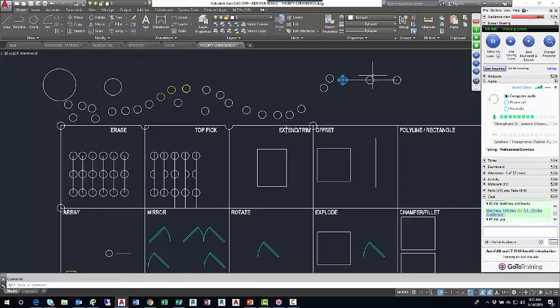So if I left click my 3 circles again, left click my horizontal line, and instead of hitting move, this time I hit copy. Go ahead and left click copy, move the crosshairs into the drawing window, and the command prompt says specify base point again. So I'll left click the center of this middle circle, and then I am to move and left click destinations for these objects.